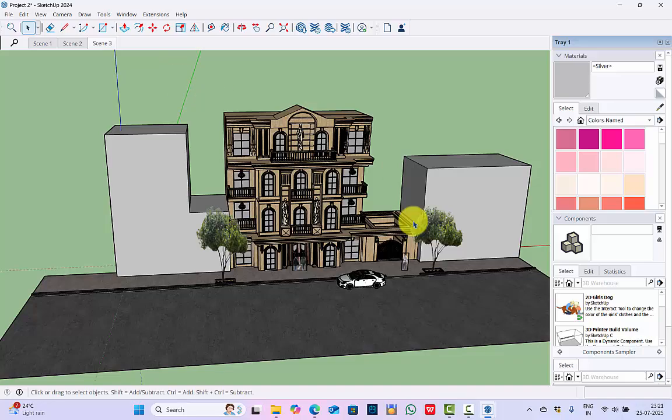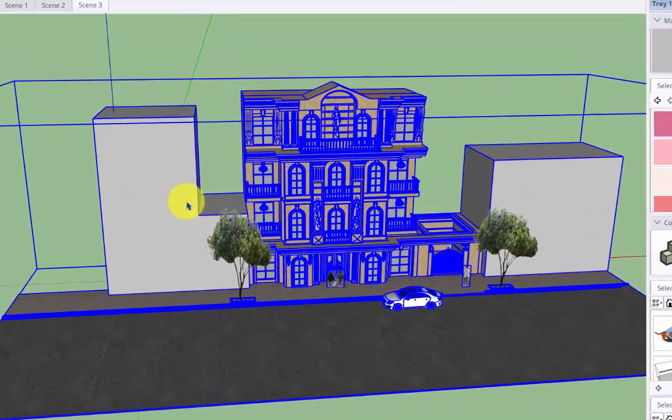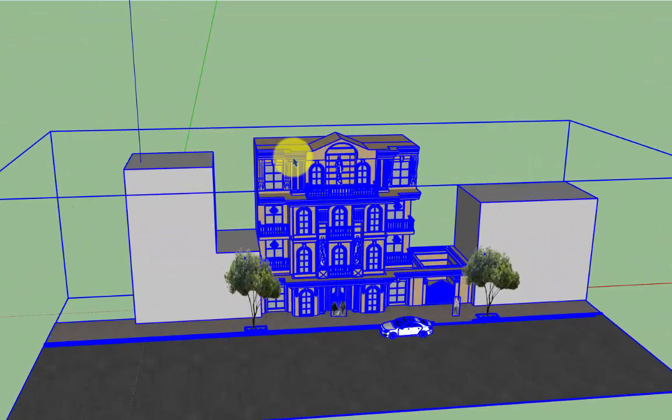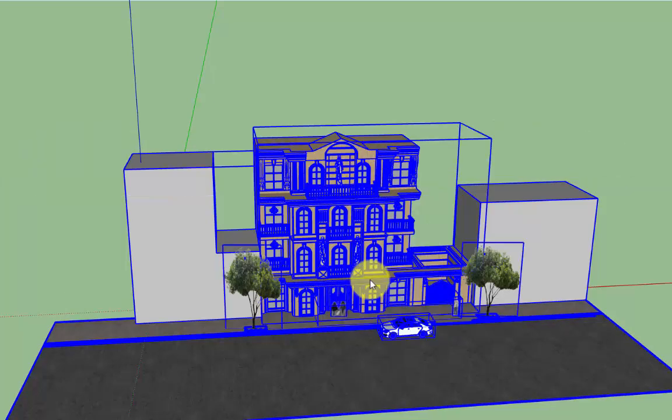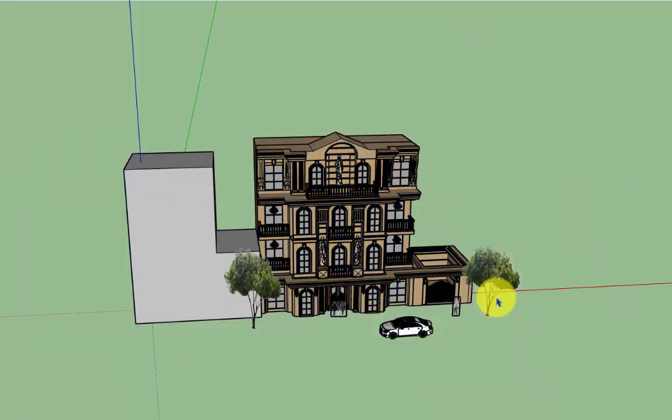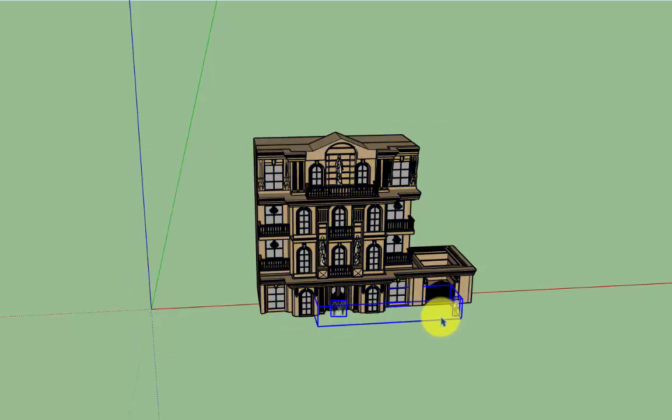As I said earlier, first thing we are going to do is clean the file. If it is grouped as one, select, right click and explode. Then select individually and delete it. This file doesn't have too many things to be cleaned.